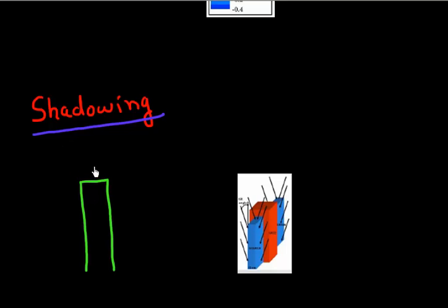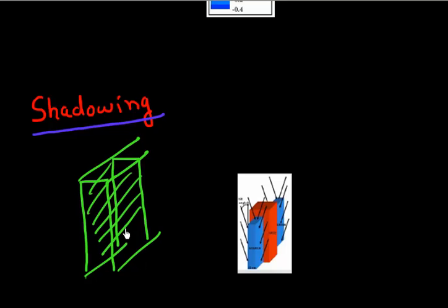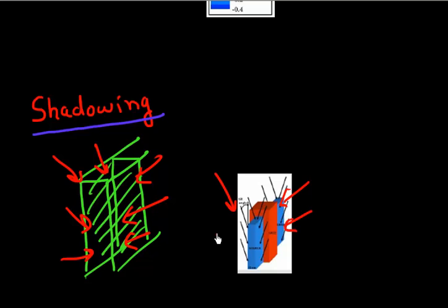Since my junction is this entire region, I need a constant, uniform doping in this region, and to do that I need to implant along multiple directions, so that I get dopants from the top and I get dopants from the side. I want to dope this entire fin with the same concentration of dopants, and that requires me to do this implant along multiple angles. So this is where things start to become problematic.